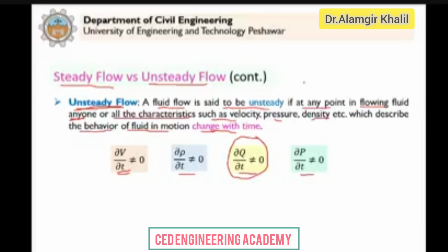We treat the velocity as one dimensional and simplify our mathematical analysis, and it was very good because we can derive the formula very easily and understand everything very well. And when we come to turbulent flow, the velocity is essentially three-dimensional. The analysis becomes very complex, and I told you that we do not have a 100% accurate model that can explain turbulent flows.